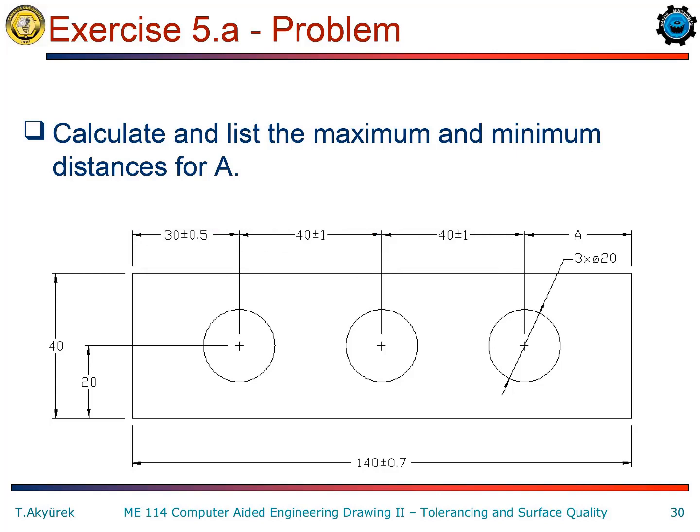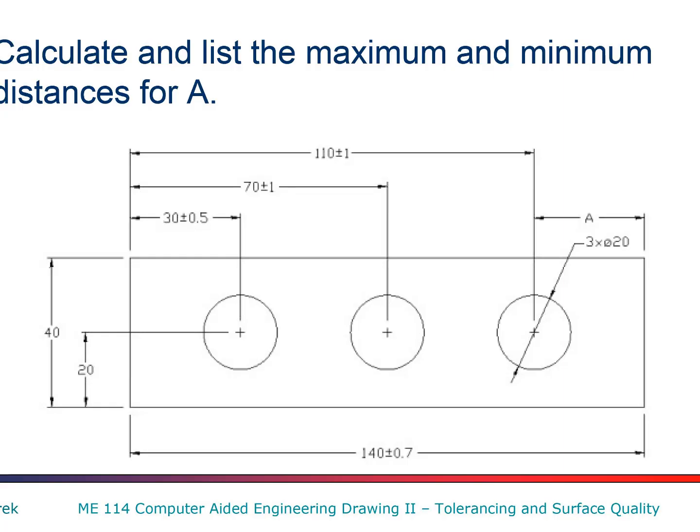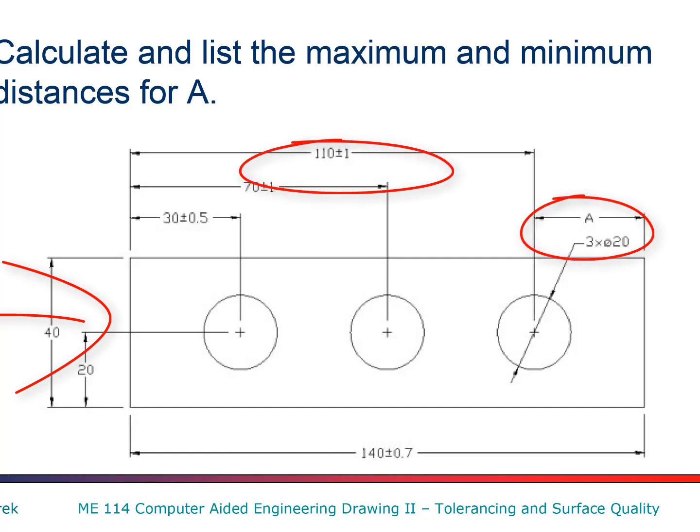In order to reduce these possibilities we must define the dimensions to a reference point or surface. This condition is called tolerance stack up, and this stack up condition must be avoided. If a single measurement is given from the left side of the part for the whole axis dimension at the far end, the whole axis size will have only 2 dimensions, with the options of 1 maximum and 1 minimum.